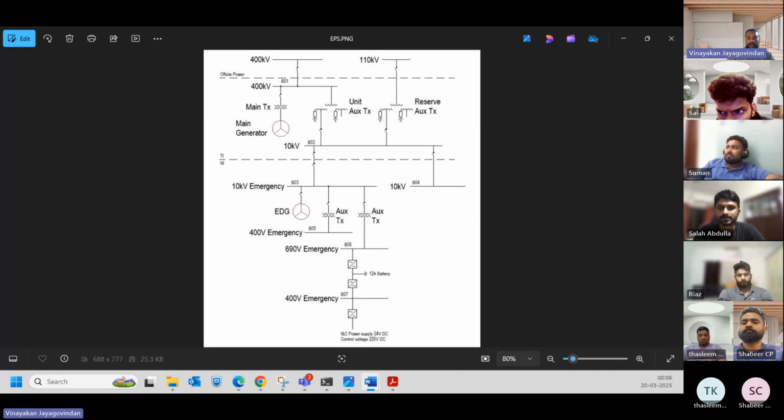When there is no offsite power, we need to load all the essential components onto this EDG. It starts supplying power to critical loads in a predefined sequence to avoid overloading the generator, and to prioritize the most essential systems in the sequence of connection, which is called load sequencing.